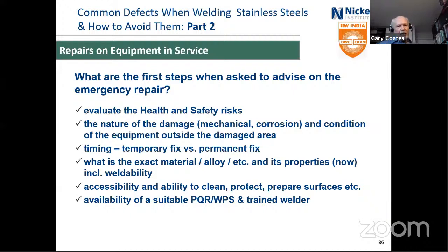So you might have an area that you're supposed to fix because that's where the leak first occurred, but you want to check, well, what about half a meter away? If it's corrosion, maybe it's just waiting to be leaking just half a meter away or 10 millimeters away. So you really want to check to see how widespread the damage is, not just what is visible, but what is actually the case.